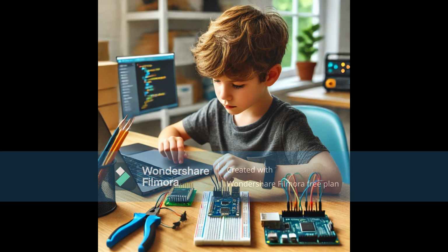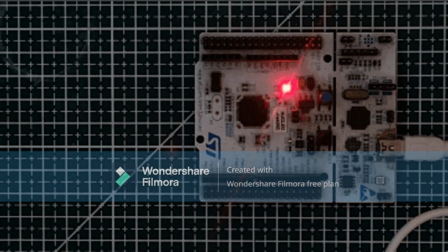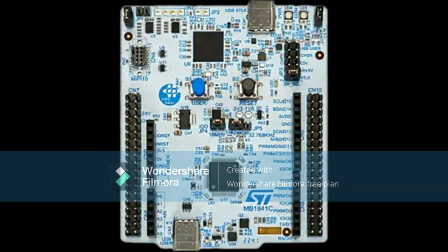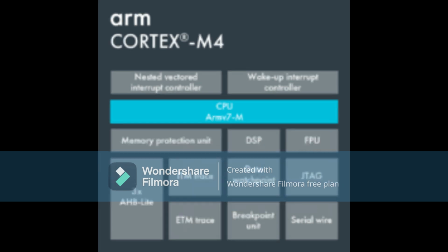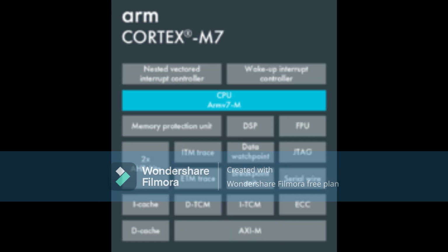Point 4, Cortex-M architecture. The Cortex-M portfolio includes different architectures, where the main ones embedded in STM32 microcontrollers are the following. The Nested Vectored Interrupt Controller is used to organize the interruptions in order to reduce the suspensions. The Wake-up Interrupt Controller, WIC, is a way to detect an interruption and wake the processor from the sleep mode. Cortex-M comparison table, from ARM.